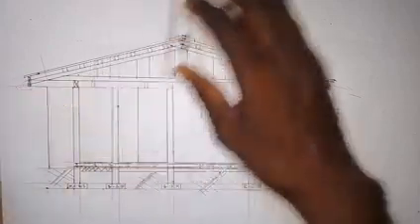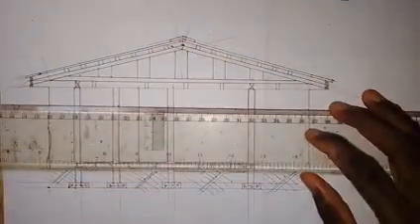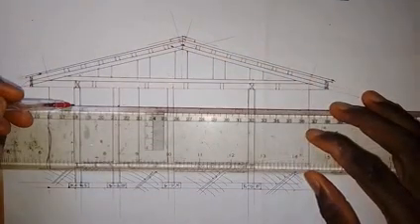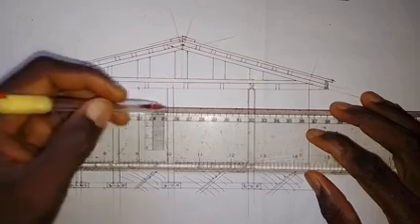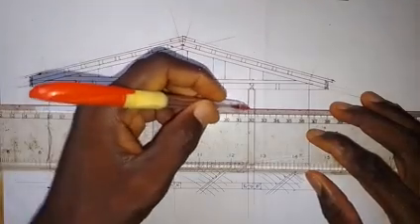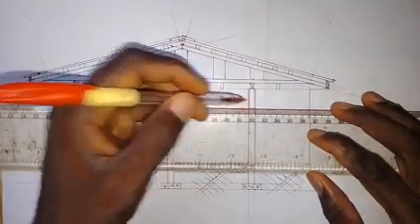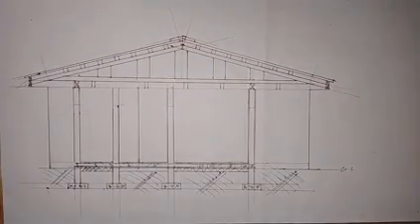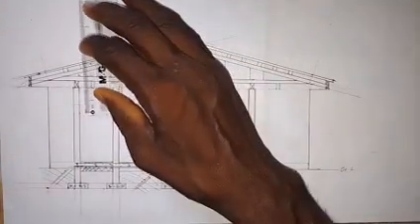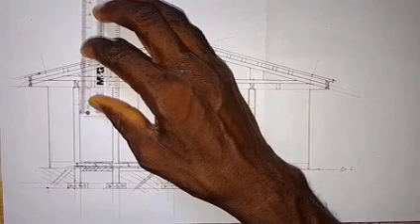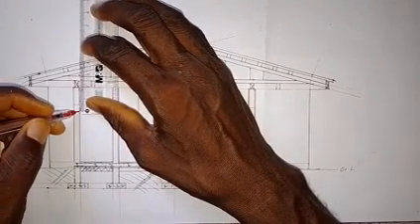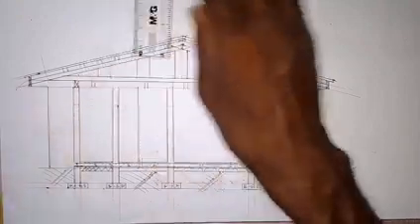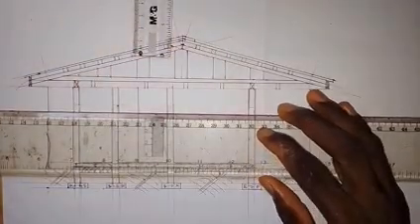So then I'm going to draw a horizontal line through this, so horizontal line here. If I have one here, horizontal line here also. So just let me put it here. All right. So then the thickness of the lintel is 225. That is 4.5, and that will give us approximately 5 millimeters. So I just take a measurement of 5 millimeters here. So we have a lintel above this window,